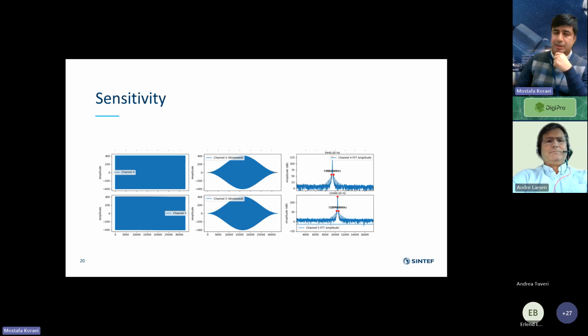I can just point out that for 8 sensors, we had around 100 megabytes per second. So you don't send that to the cloud, it would be extremely expensive. You need to do the filtering before that. So the whole purpose of using AI and machine learning at the edge with FPGAs is processing that data at the edge and just sending the results to the cloud.